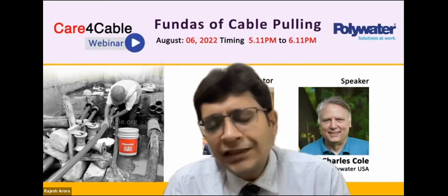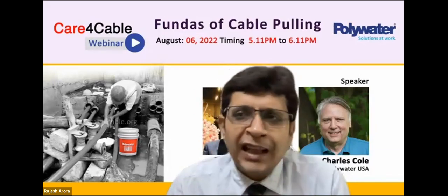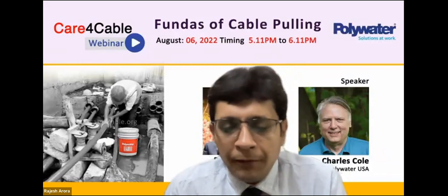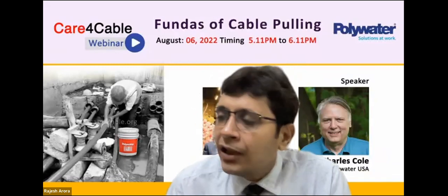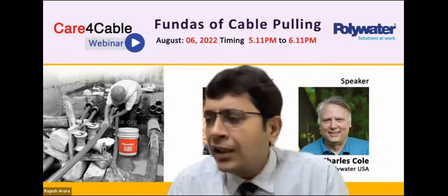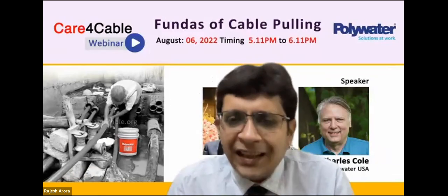And if you just look at the slides you have shown, in example number 1, when the line was straight, its length was 500 meters, you didn't mention the sidewall pressure in that straight line case. Why? Because sidewall pressure only occurs when a cable is pulled around a curve. Okay.